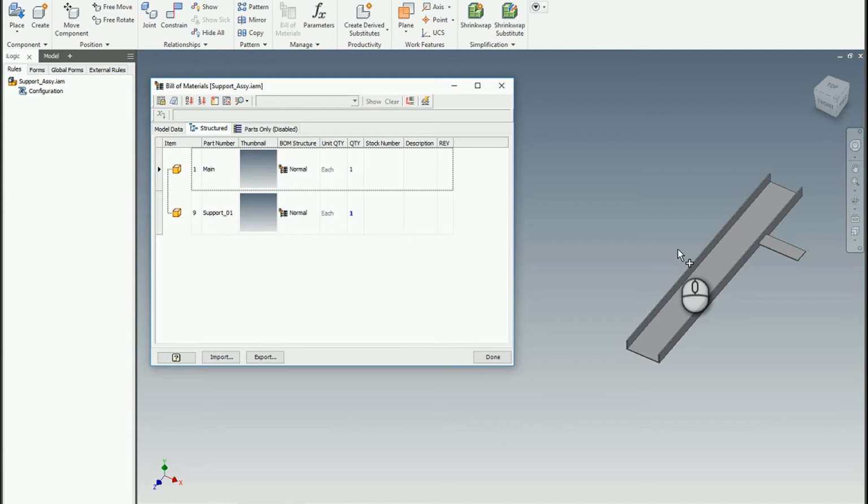So this is a great technique for that because I'm not producing part drawings, and I can reduce a very complex assembly down to a more simplified part driven with iLogic rules that also can control the explicit bill of materials. So I hope you find this tip helpful.